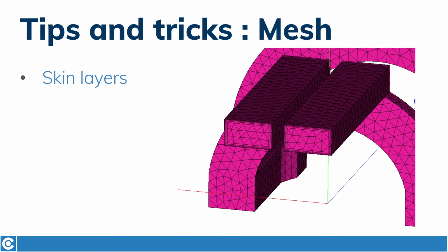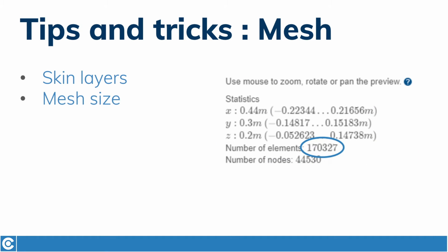Pay close attention to the mesh size, especially for 3D simulations. If element count goes above 300,000 elements, consider simplifying your simulation through geometry or symmetry, as simulations with large mesh will take much longer to calculate.